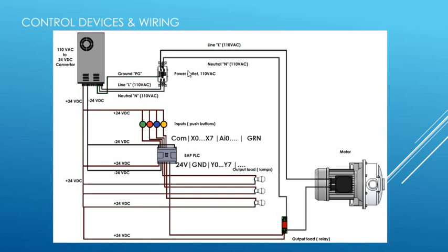where different power outlets have breakers that help you to control. Whenever the AC amperage is higher, the breaker or fuse might burn and you might need to change it. It might trip. And the relay is the same thing as the bulbs. So you have 24 volt coming to the coil part of the relay, and in the coil you have plus and minus, so you connect this one to the plus side, and the negative side is connected to the output of the relay. Because of that, as we said, this is called a sinking output.